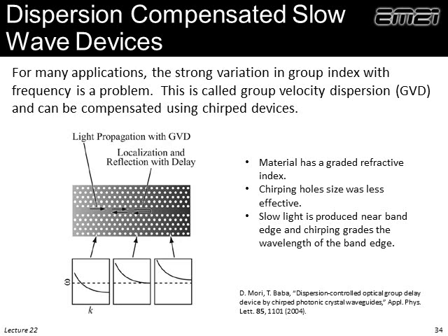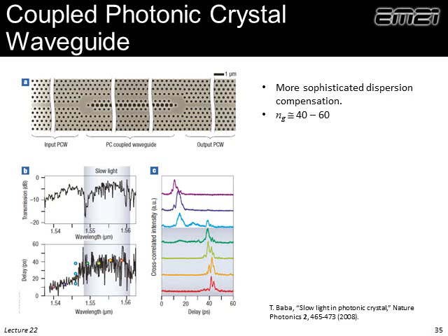It turns out that the group velocity can also change as a function of frequency, and very often we want to control that in some way. Maybe we want to make it constant, or at least a linear slope. So the way this is done is we take our slow wave device and we chirp it. So it essentially affects each frequency in a different portion of that slow wave device, if you will. And we can flatten the group velocity dispersion. We can do other things.